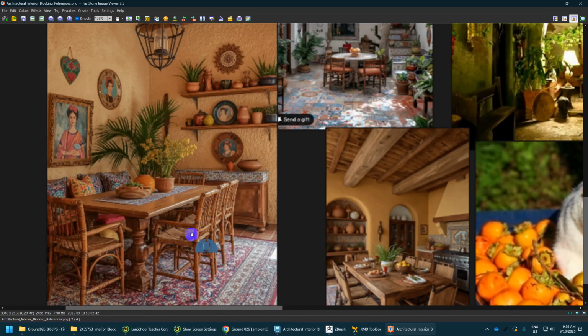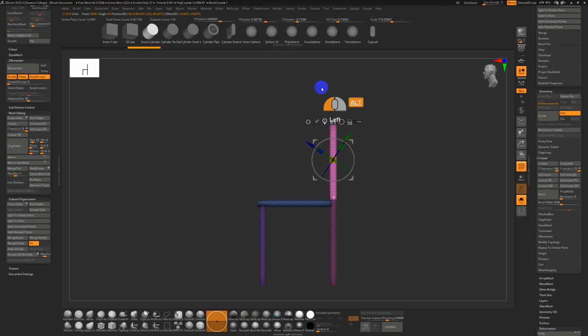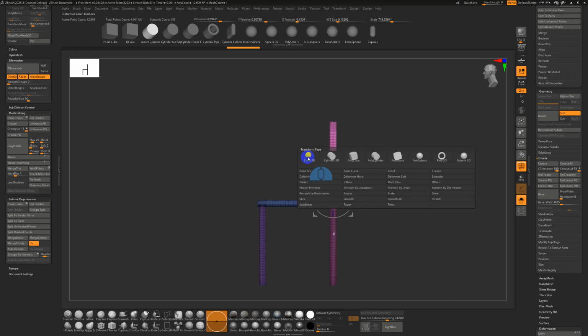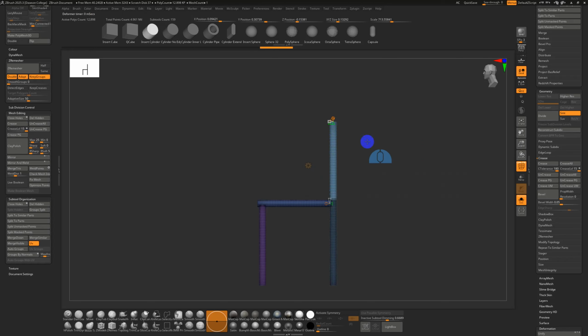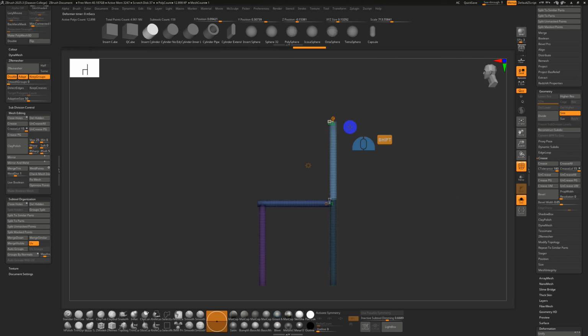Right, these things kind of curve out a bit. So I'm going to just control click and flip the mask around. I'll alt click on the pivot again and center it. And if you click on this little gear icon, it actually gives you a lot of direct deformers or modifiers. So if I go to bend arc, for example, again, very kind of strange tool to use at first.